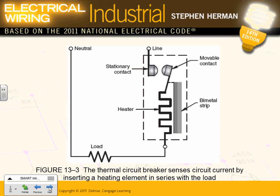The current goes, if this circuit, this is my load, if this circuit is supposed to protect you, if this is a 15 amp circuit breaker, and now we're pulling out of that boy a 20 amp. Look what happened. You're pulling a 20 amp out of a 15 amp circuit breaker. This heater starts creating more heat.